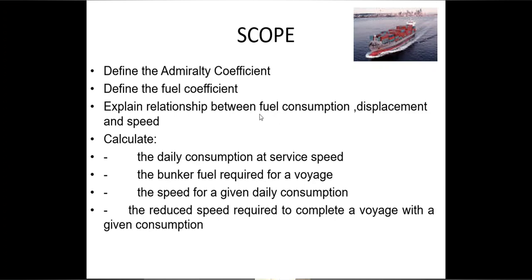On the basis of the Admiralty coefficient and fuel coefficient, the first two coefficients on your screen, they will be used to calculate the daily consumption at service speed. So when the vessel is sailing, how much fuel will be consumed in tons? Consumption is measured in tons per day. Then the bunker fuel required for a voyage.